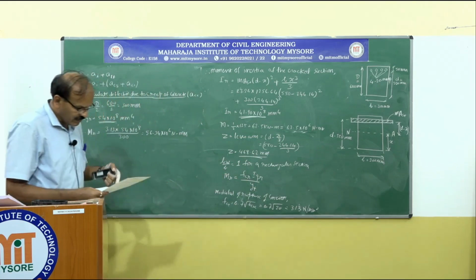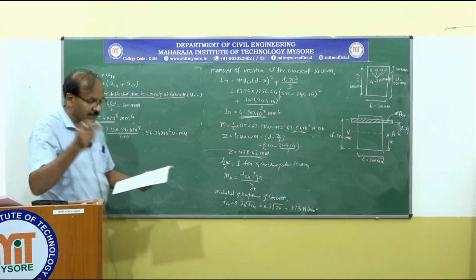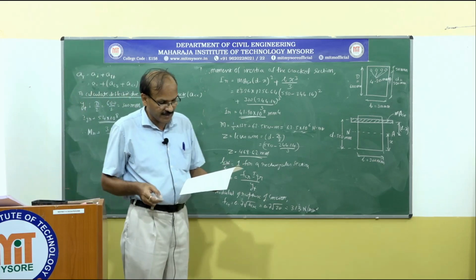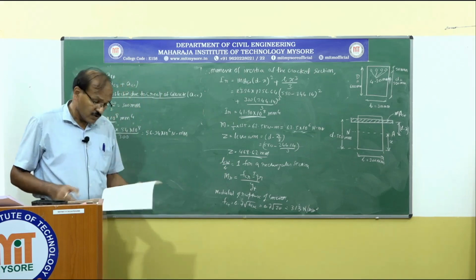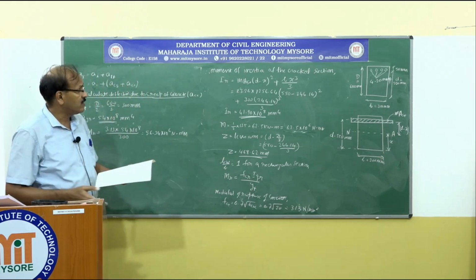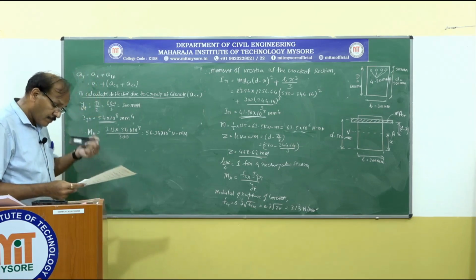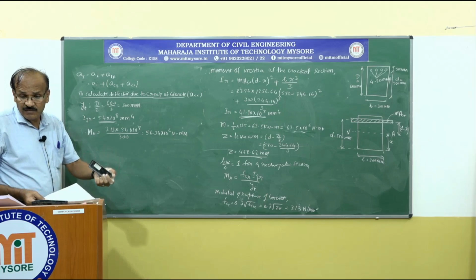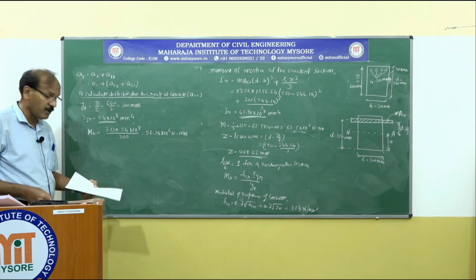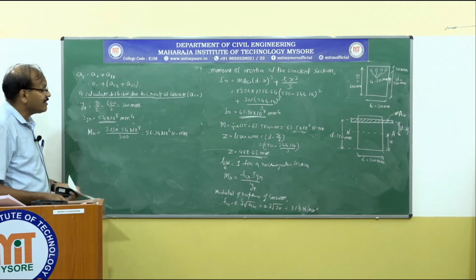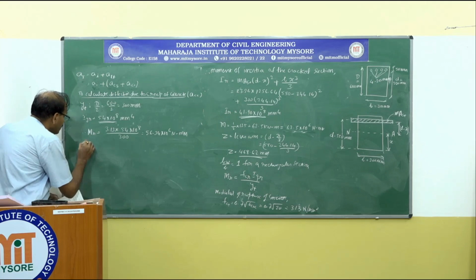So if I go to that equation, I effective equals Ir divided by 1.2 minus Mr by M, times z by d, times 1 minus x by d, times bw by b. We know all the values, so we substitute all the values in that equation, given in the code on page 88 under C.2.1, to get the effective moment of inertia Ieff.